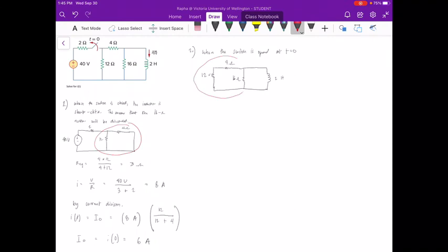We need to obtain the value of this resistor network again. So our Req, which is our encircled network, is a combination of series and parallel addition rather. So you have the resistors in series, 12 and 4 ohm resistors, times its parallel resistor, which is 16 ohms, over the addition of these 3 resistors. Calculating that would yield 8 ohms, so that's our equivalent resistance.